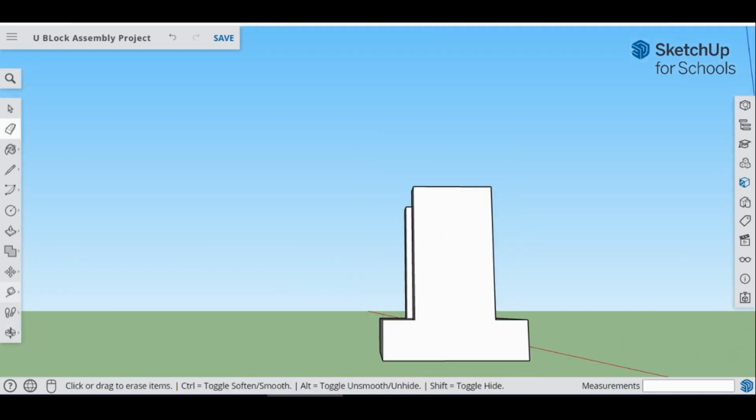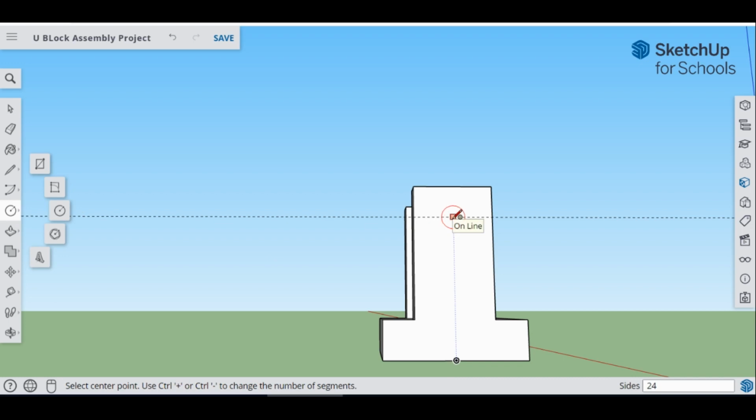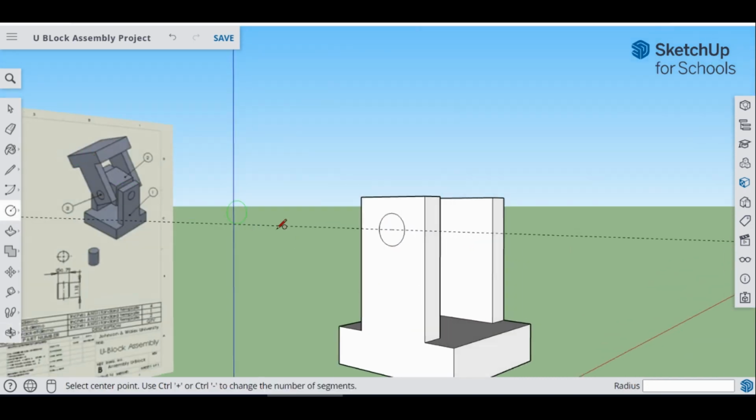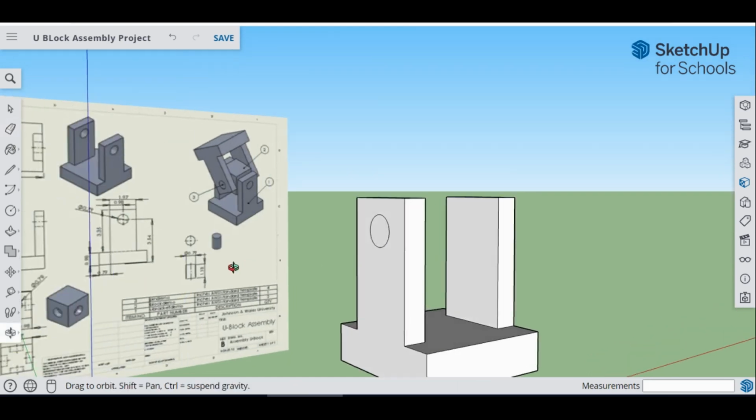So you're going to make sure that you have your tape measure tool from the center point. You're going to measure up. Make sure it shows that blue axis. You're going to type in 3.54. Gives you that reference, circle tool, center, and then we're doing the radius again of 0.395. Hit enter. That's the E on the keyboard for that erase, and now we're there.